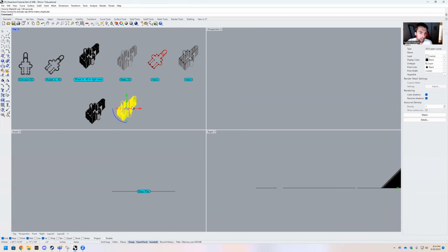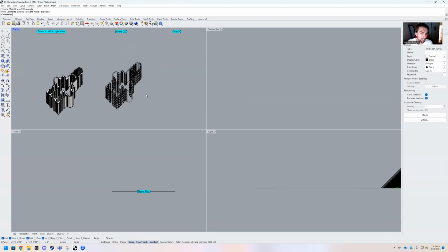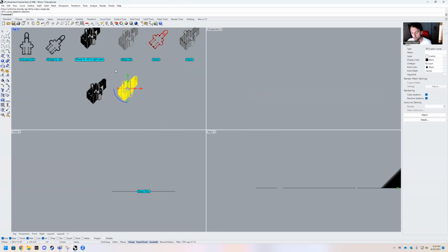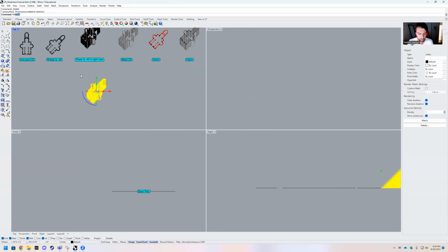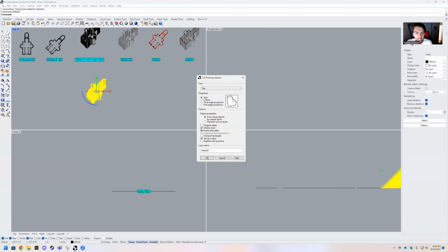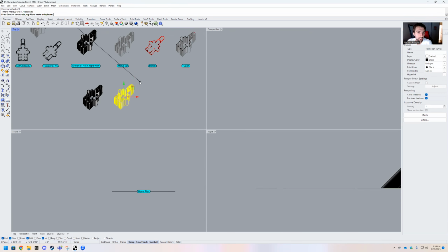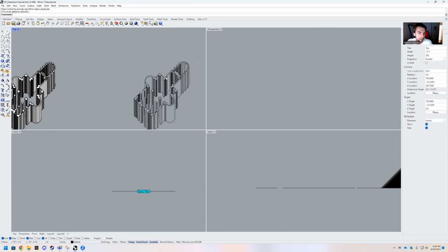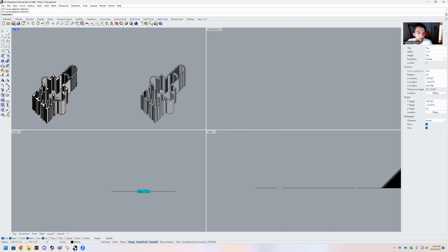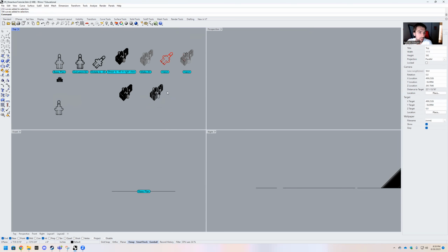It generates for us some lines. And it looks like this time around it generated some hidden lines. So we're going to delete that. Type make 2D again. And if you see this options box, once you have it set up the way you want it, you can hit enter through it really fast. But the first couple times, give it a look, turn off hidden lines, hit enter. So now we have this line work that we've generated. And you can see it's actually grouped by 3D object because that was one of our output options.